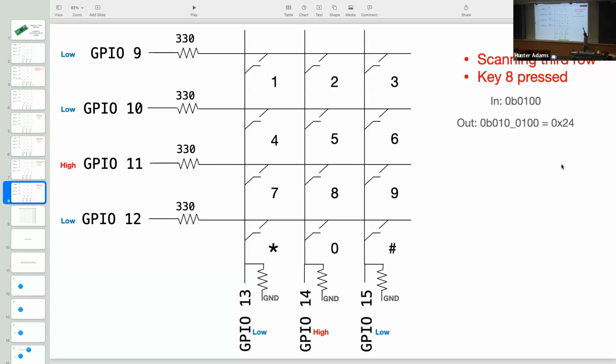This is the source of some of those cryptic looking scan codes and key codes and so forth. All that we're doing is translating our GPIO state in a number of different conditions, where each of the separate buttons is pushed, to hex codes, and what we get is these somewhat cryptic looking key codes coming out.